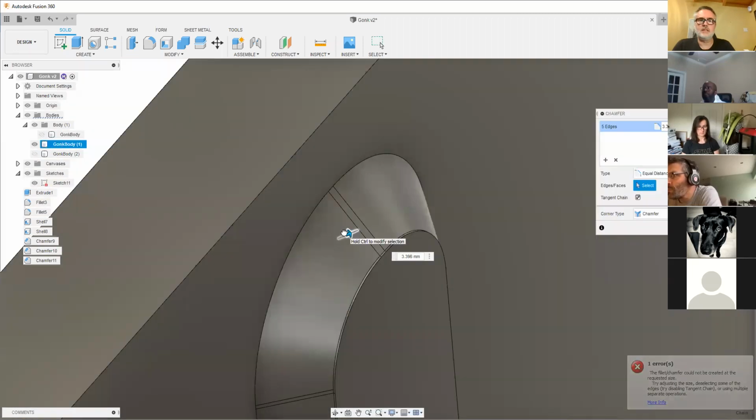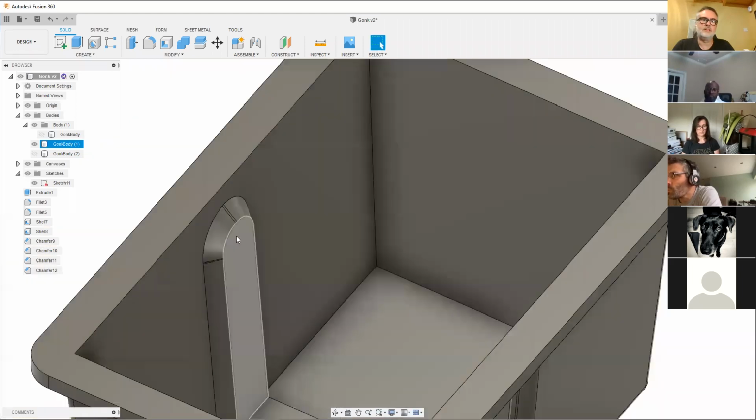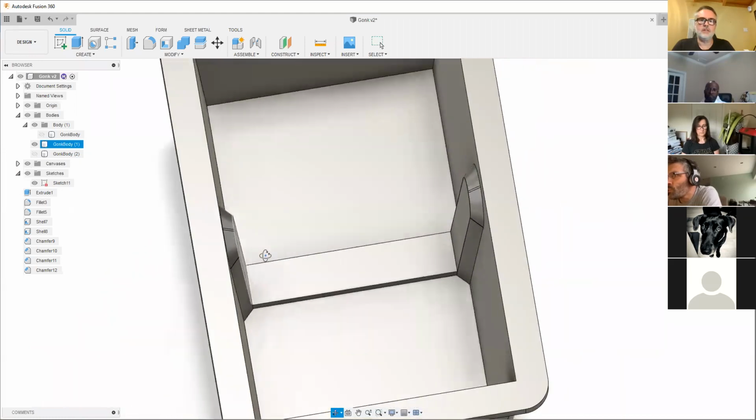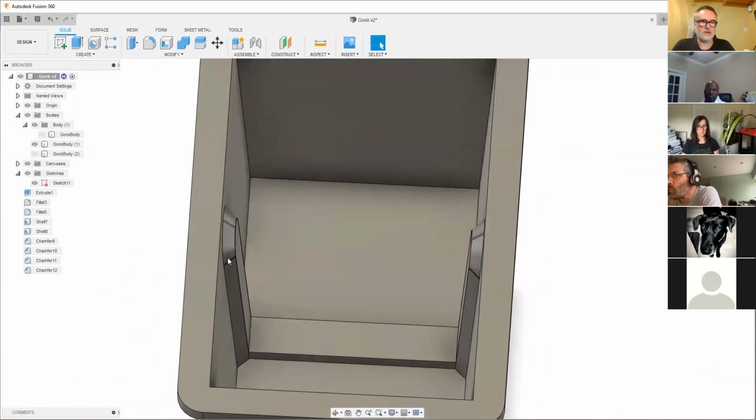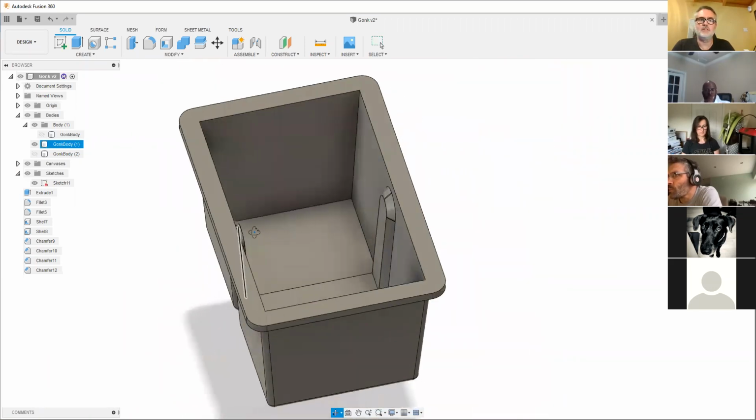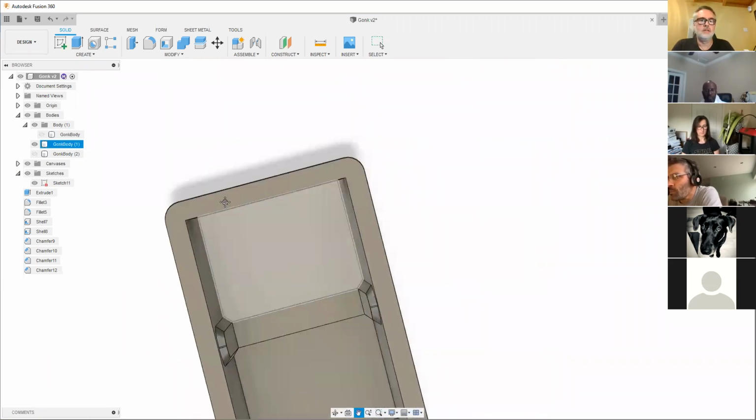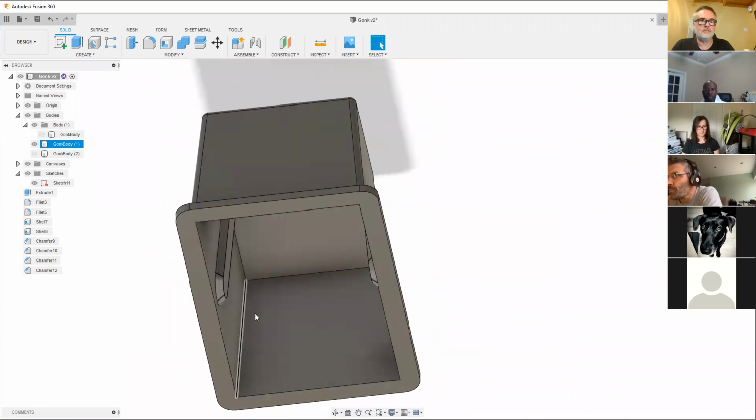And this is the advantage of doing direct modeling, which is what I mentioned on the first one about turning the timeline off. It gets really complicated if you've got the timeline on when you're doing little iterative steps, or you're just adding little bits and bats like we've been doing. So I'd always recommend that you do that.